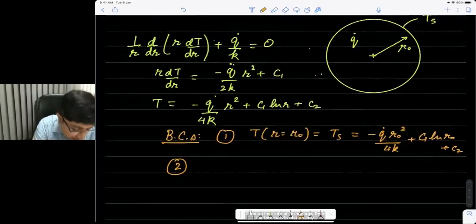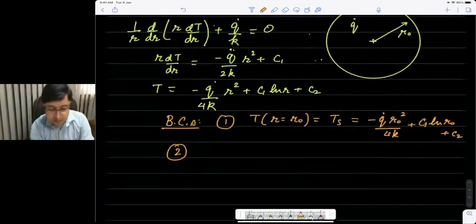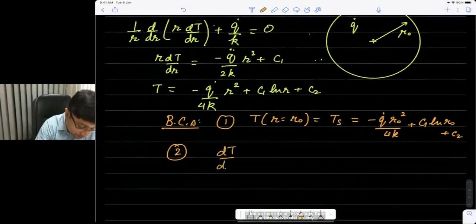Okay, so let me interject and say that r is one coordinate which only goes from 0 to infinity. It doesn't go to minus infinity. It's not like x, y, and z coordinates. R only goes from 0 to infinity. So the problem that we are facing is definitely at r equal to 0. What should we do at r equal to 0? So you are right that we can take dT dr at r equal to 0 to be 0. But the logic for that, I will also say, is from symmetry.